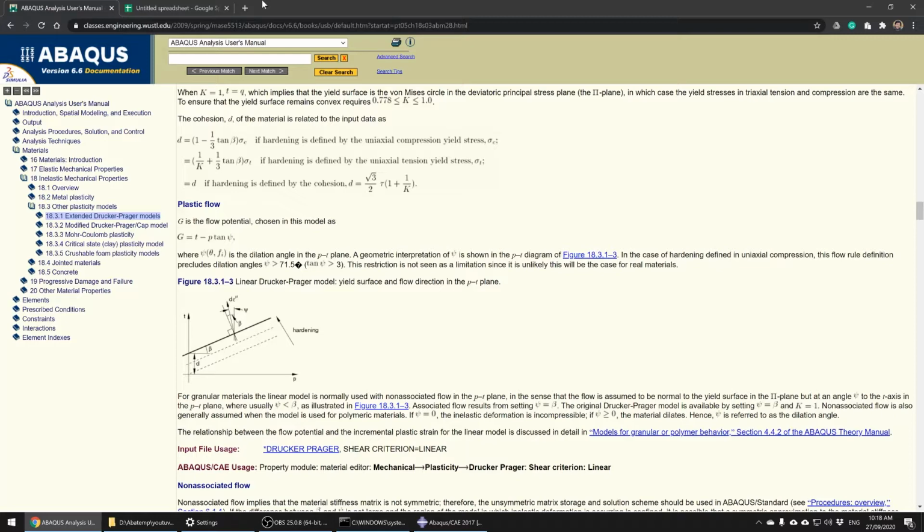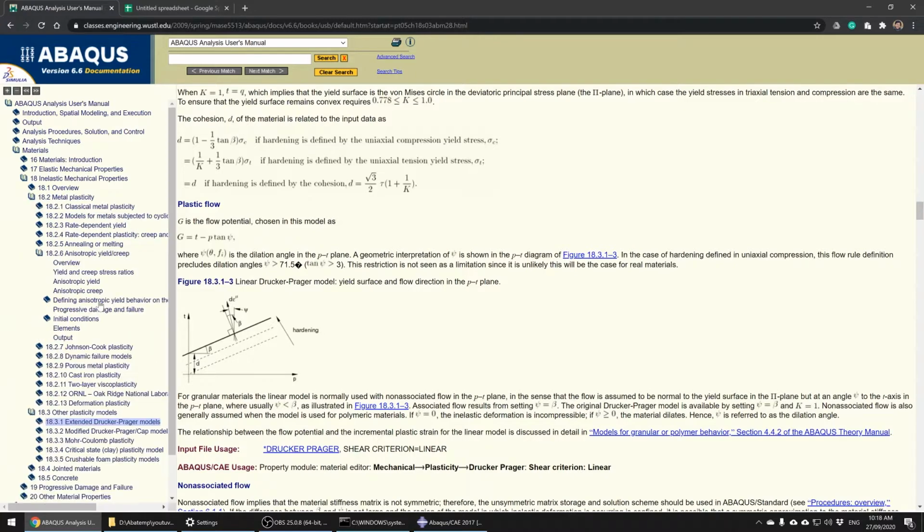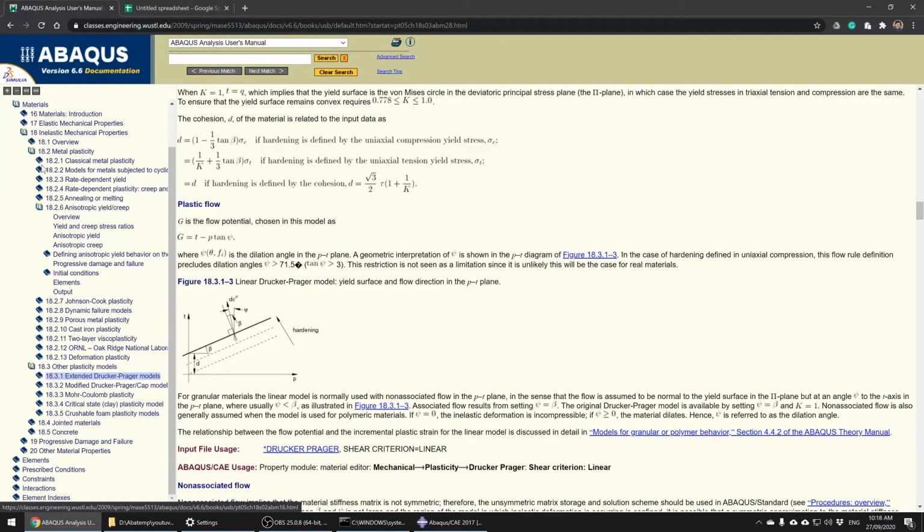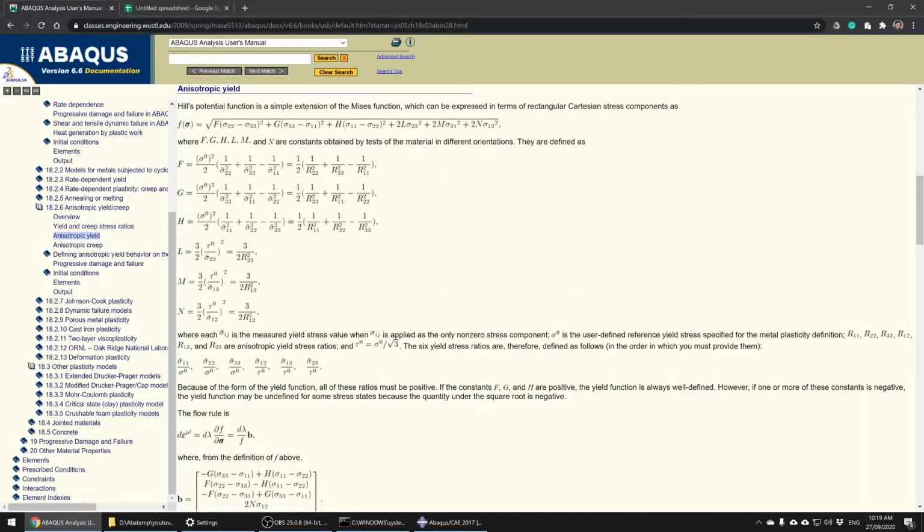All right. Usually, people model plasticity in metals using the von Mises criteria, von Mises plasticity, because it's very good. But for sheet metal forming, where the sheet has been through a rolling process, there is slight anisotropy in the rolling direction compared to the transverse direction. So the plastic yield strength is different. In that case, you need to use anisotropic plasticity. For example, in ABAQUS, we have what we call, let me check here, the Hill yield function. I'm not sure here, but it should be there. Yes, for example, this one: ABAQUS has an anisotropic yield function following the Hill potential.